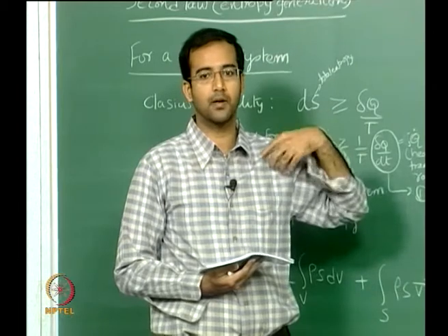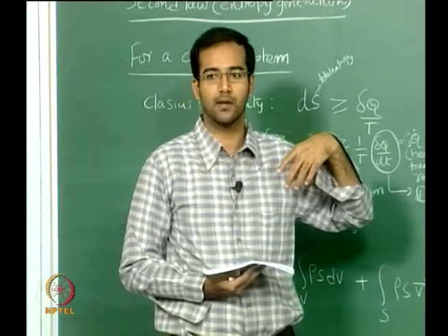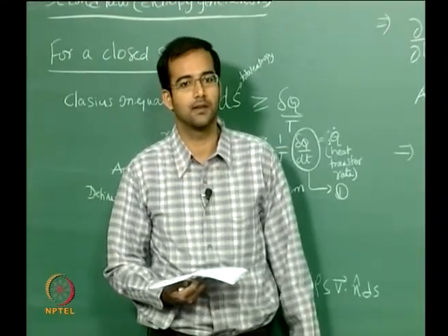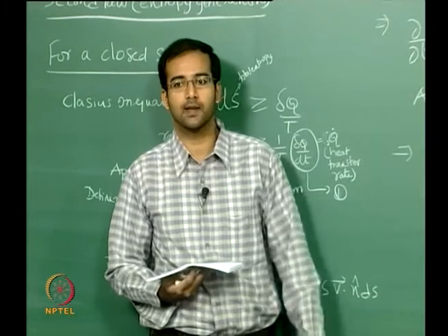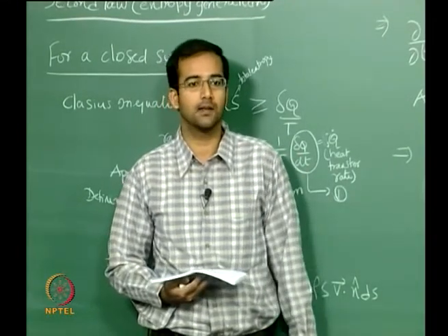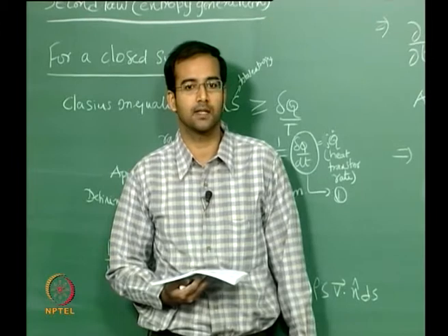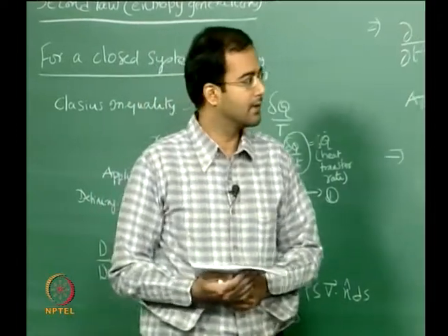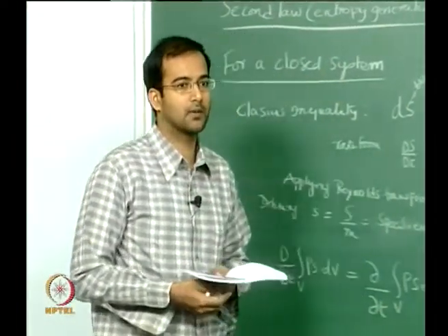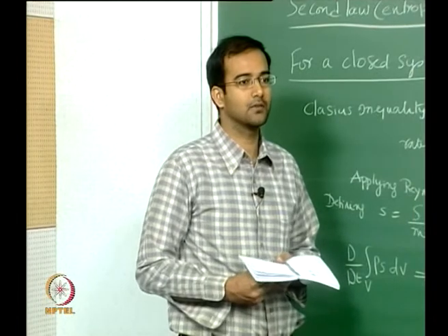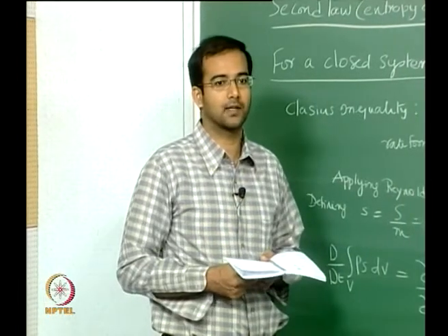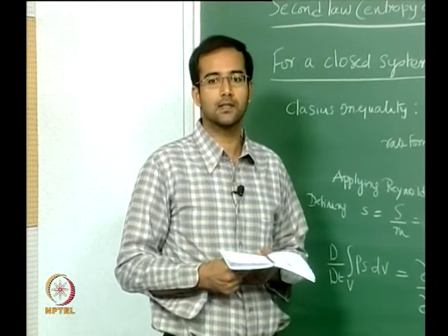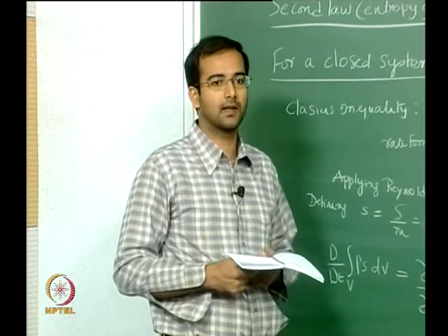Okay, now we don't have a separate equation for pressure. We have equation for u and v and continuity equation which is like a default equation. So therefore numerically there are some techniques to overcome this hurdle where we construct an artificial pressure equation and things like that. If you want to overcome that, we can rewrite the Navier-Stokes equation into what is called a stream function vorticity formulation. Okay, and that is very useful when you are looking at 2D incompressible flows. There you have only 2 variables, 2 equations. You can solve that straight away, and the solution is also slightly simpler than solving the Navier-Stokes.